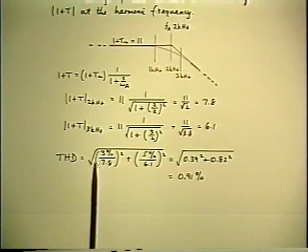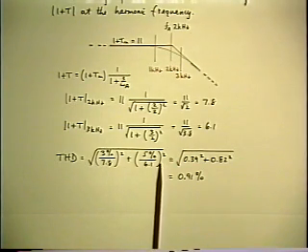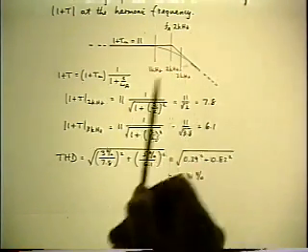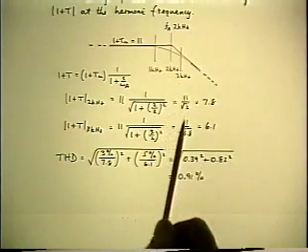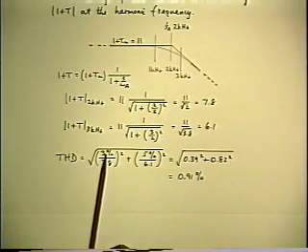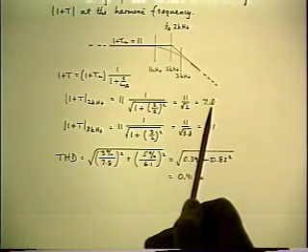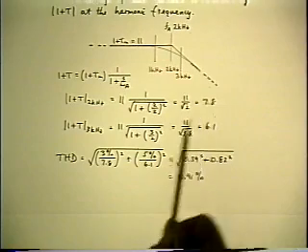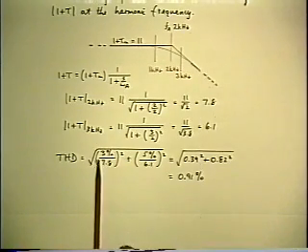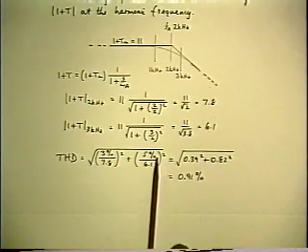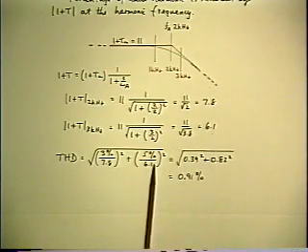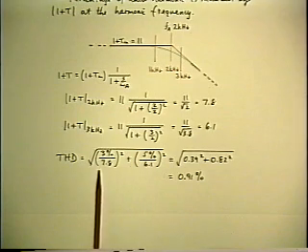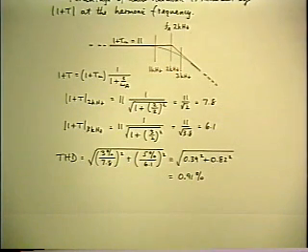The RMS combination is the root of the sum of the squares. So in this case, we only have 2 harmonics specified. So the second harmonic originally was 3%. Now it's going to be divided by F at 2 kilohertz, which is 7.8. Then you square that. And then the third harmonic was originally 5%. That gets divided by 6.1. Square that. Add it to the first one. Take the square root, and the result is a little under 1% THD.